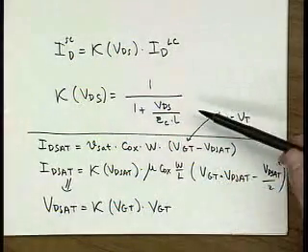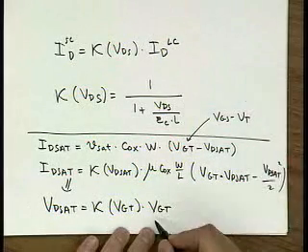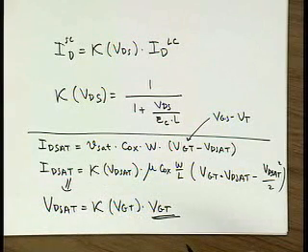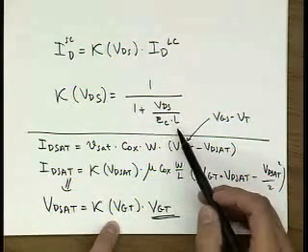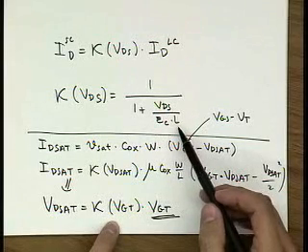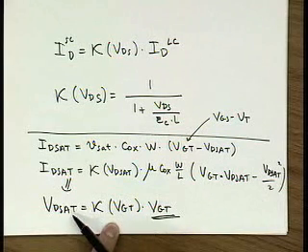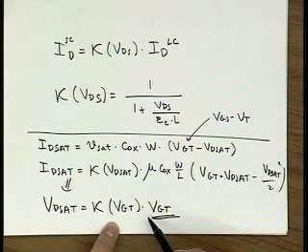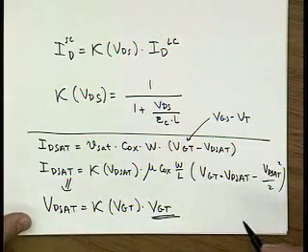So we see from this expression that for the short channel effect, and this VGT was basically the boundary where saturation point for the saturation point in your long channel transistor. So you can see from this expression, plugging it over here, that for a very short channel transistor this value is much less than 1, which tells you that velocity saturation, it's another way of saying that velocity saturation occurs before the saturation in conventional devices. That's the important point to remember.